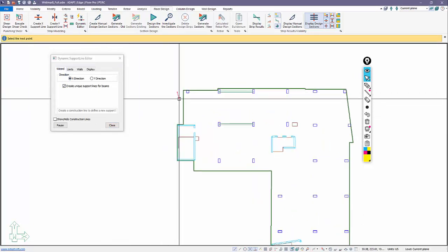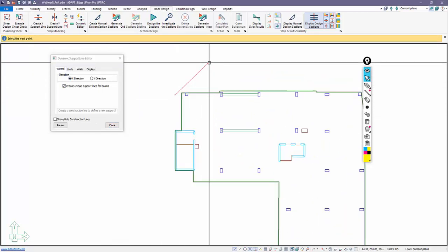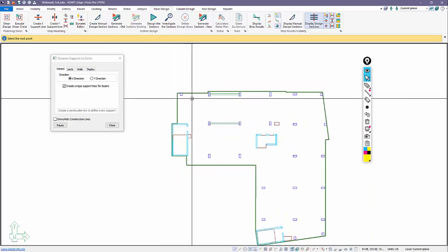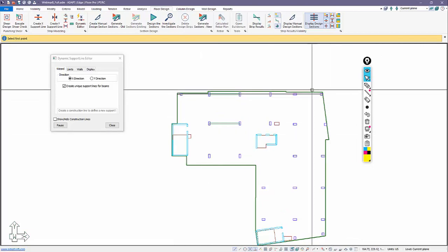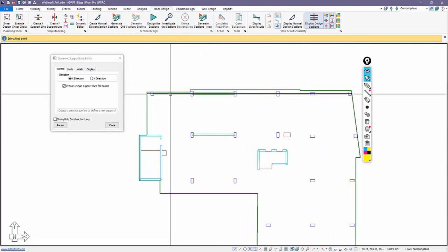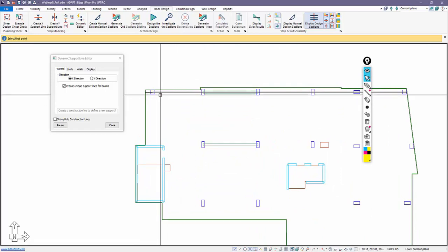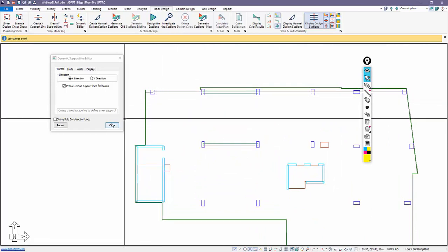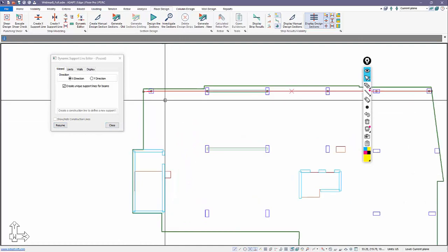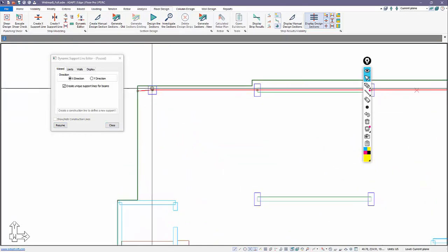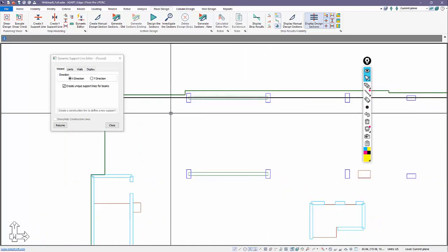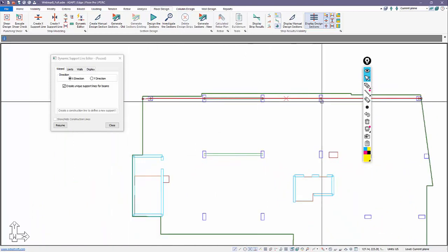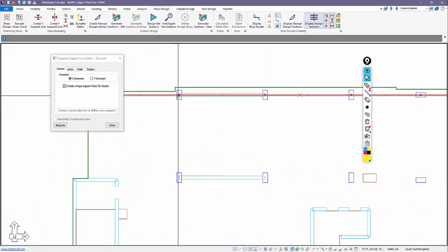So I'm going to click a line here. This is a red, we call it a ray, and the ray will be snapped. If I just simply go all the way along here, the program will pick points along that ray, and you'll notice that it places a point. Let me close out of here. I'll pause this. It places a point at the slab edge, supports, and beam. Notice that this is still continuous. It does not actually break the beam out.